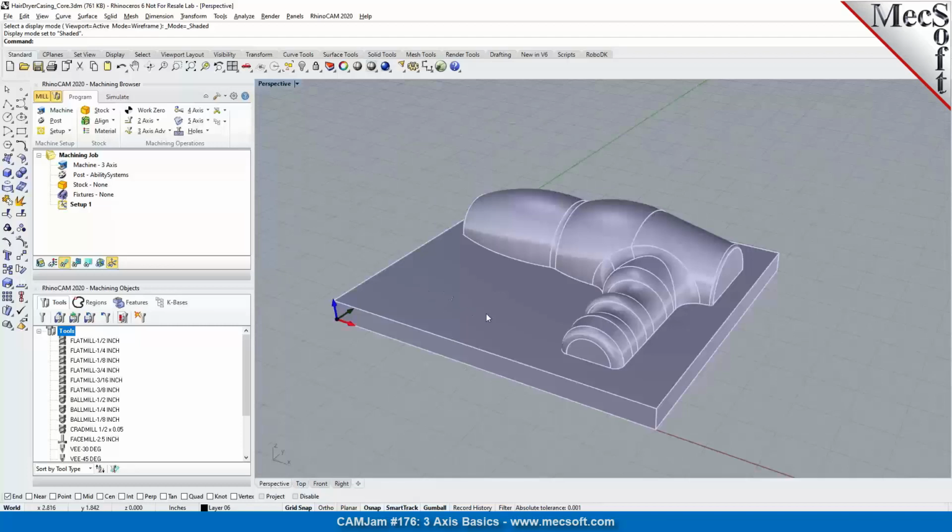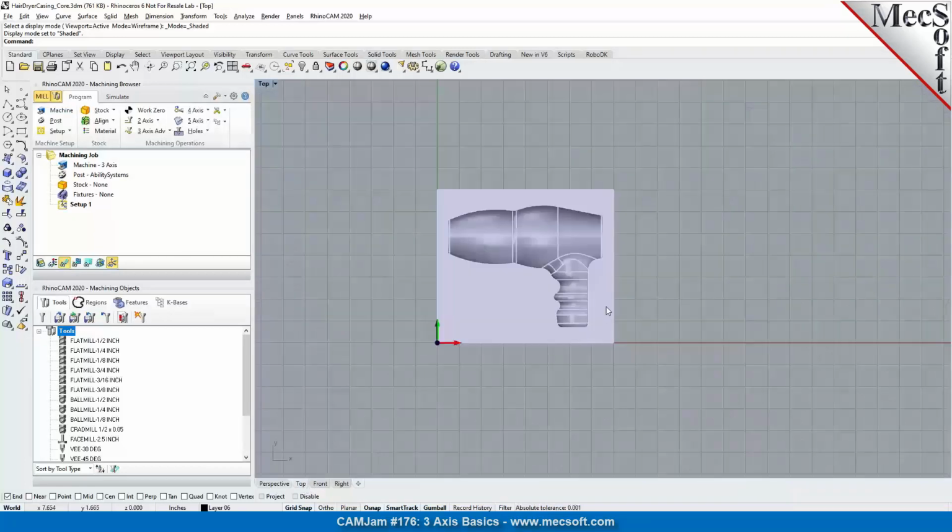So the z-axis is normal or perpendicular to this planar face that you're looking at here on the model. So that would be the orientation you would like to mill it from. Now, if you need to rotate the part to fit the work envelope of your machine, you could orient it using several different tools that are available to you, either using the CAD tools that are built into the host CAD system. We can select the geometry and use the rotation command using the gumball.